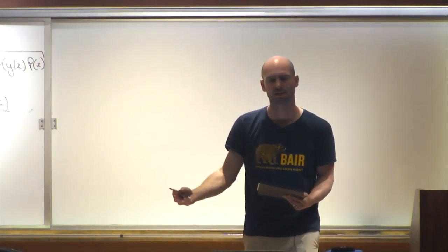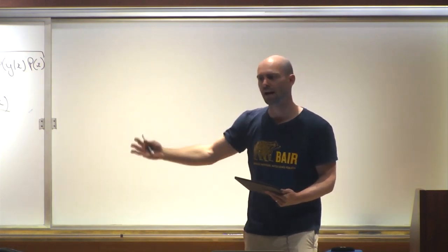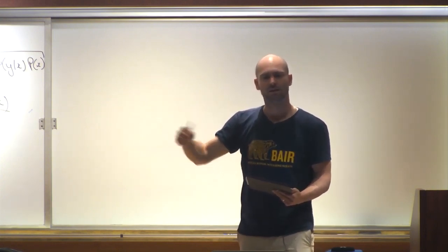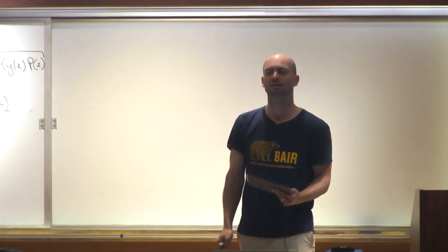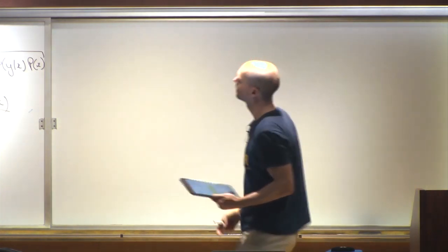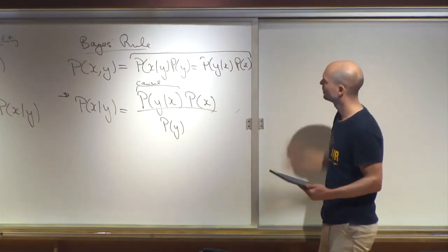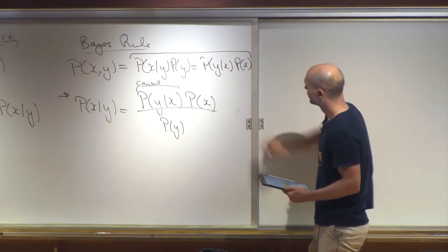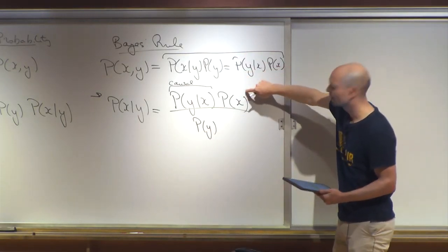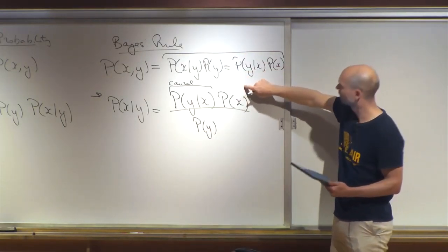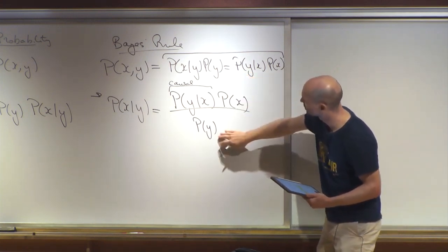For example, for a laser rangefinder, you might say, well, if there's a flat surface at a certain distance, the reading you'll get back is within maybe 2 centimeters, like maybe a Gaussian with standard deviation 2 centimeters around the proper distance reading, something like that. So that thing is your calibrated sensor, and that you can get a distribution for. But what actually ultimately will be the distribution over state, given that reading, will depend on the prior p(x), what you thought ahead of time might be likely states of your system. And so they combine together. And then, of course, there's a normalization to make sure things sum to 1.